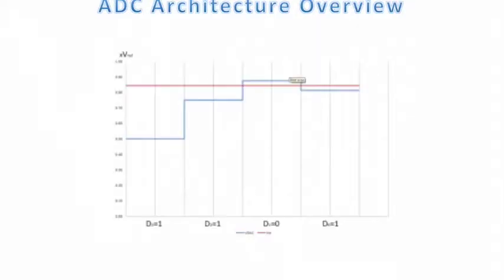To describe the functionality of this architecture, the analog input is fed into the S&H block, which you saw before in the previous slide, and is being tracked and held. Once it is, our main logic is performed by a binary search algorithm. This algorithm is implemented by first setting the n-bit register to a mid-scale value where the MSB is 1. This forces the DAC output voltage to be Vref divided by 2, where Vref is the reference voltage provided to the A to D.